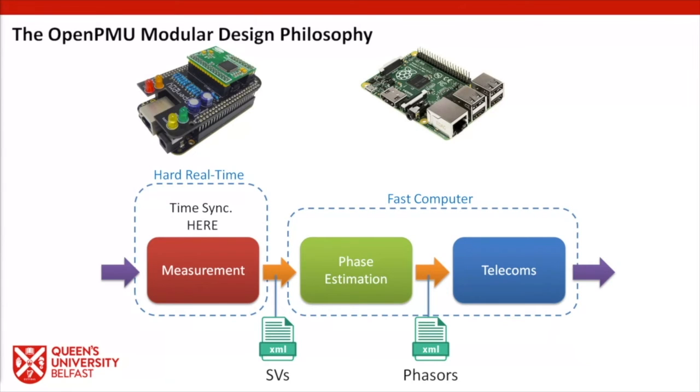And because these programmable real-time units share memory space with the Linux host operating system, these small co-processors, running assembly in our case, and one of them has a little bit of C++ in it, those functions can control the analog to digital converter, which sits on a little daughter board, and can pipeline the sampled values from that analog to digital converter at known instances in time into a shared memory buffer, and the Linux host OS can then start processing that asynchronously and pipeline that data off to the rest of the functions.